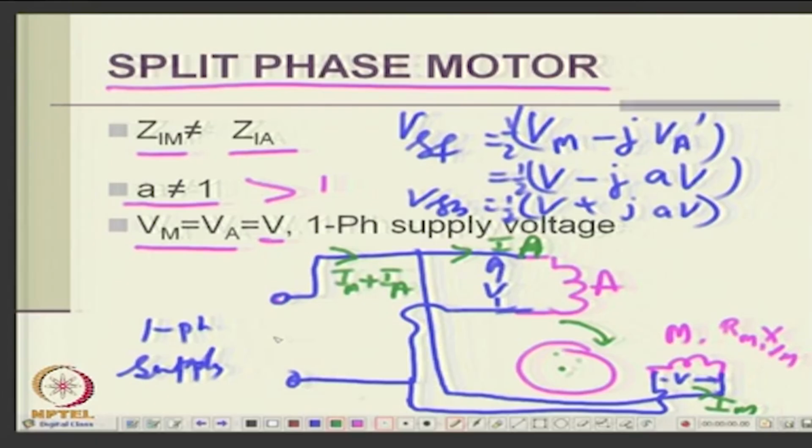So, you have the split phase machine, so you can always find out various things. You can always say this is V, this is I. You can also calculate the power factor. If you know V and I, you can calculate the power factor, you can calculate input power, you know the developed torque, you can calculate the output power, then you can calculate the efficiency of the motor. So, you can develop the whole program, a computer program in which all this can be estimated.